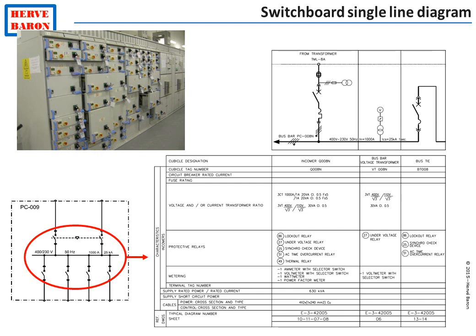To order a switchboard, it is necessary to specify what type and quantity of incomers and outgoers are to be part of the switchboard. In addition, the types of protections, i.e. circuit breakers, to be provided for each incomer and outgoer must be specified together with their rating. The type of protection is specific to each type of consumer. For instance, an electric motor will not require the same type of protections as an electric heater.